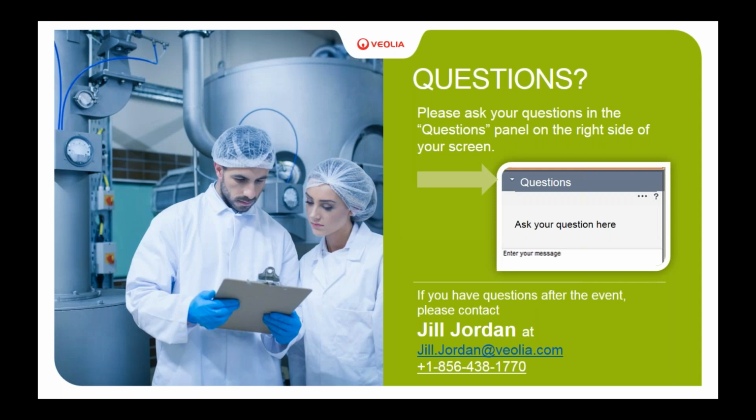Every plant is different, and every pH probe in the different locations is different. So the influent pH probe may only need to be cleaned once a month or something, but the effluent may need to be done once a week. Everybody's different. That's why you check it every day. And the really important ones are where you're doing your pH control and in the reactor effluent. Those are the most important ones to really, really keep an eye on.